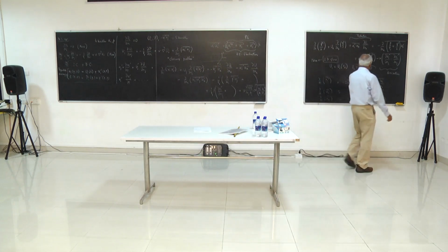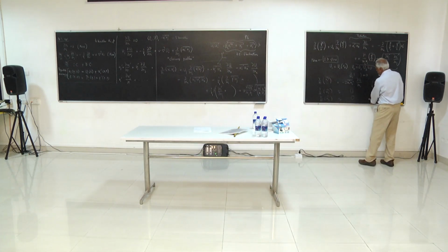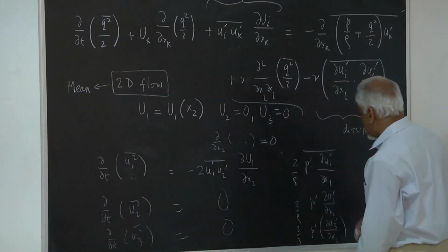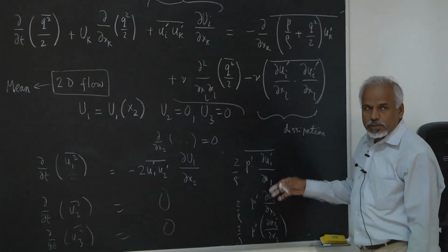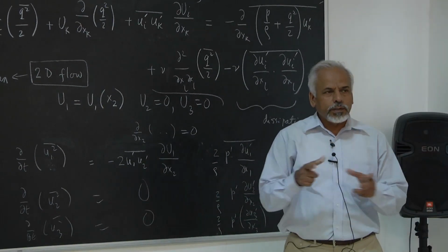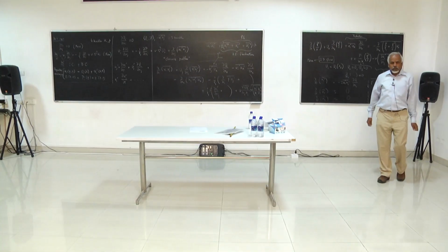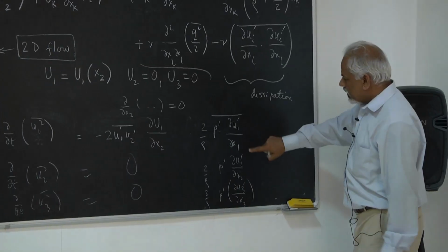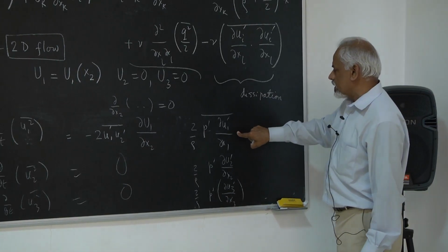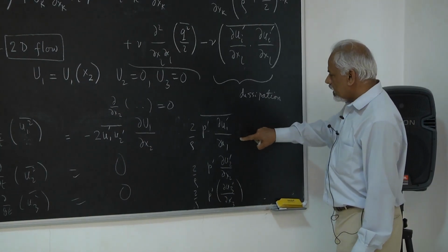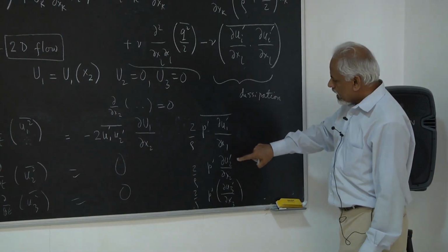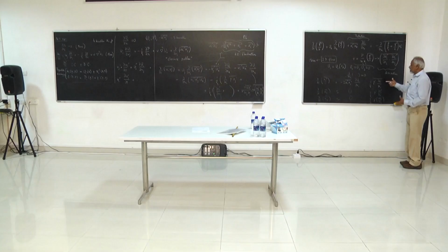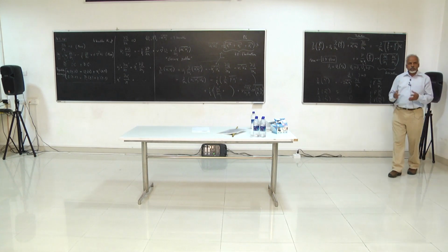So what this says is, if you sum it all up, if I use u1 squared, u2 squared, u3 squared, etc., the contribution of the pressure terms is 0. That is, if you looked at all three of them, it means nothing. But they're sharing from here to these two. So this is always a negative quantity, and these two are positive quantities. So the pressure somehow distributes energy among the three.